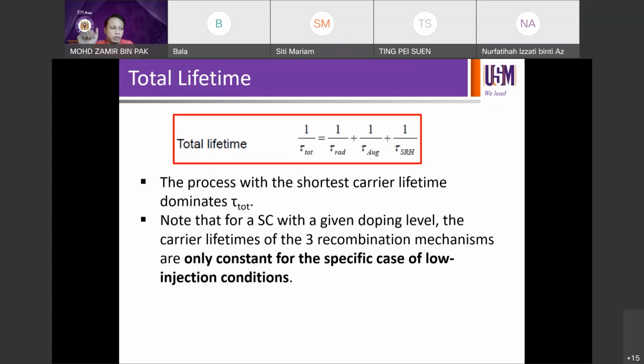So typically, if you're working on a material with a high lifetime, for example, say I have a silicon wafer, and the lifetime of my silicon wafer is 300 microseconds. So the order is typically around microseconds, nanoseconds. It depends, right? Microseconds, if you talk about silicon, is considered good. Hundreds of microseconds is considered good.